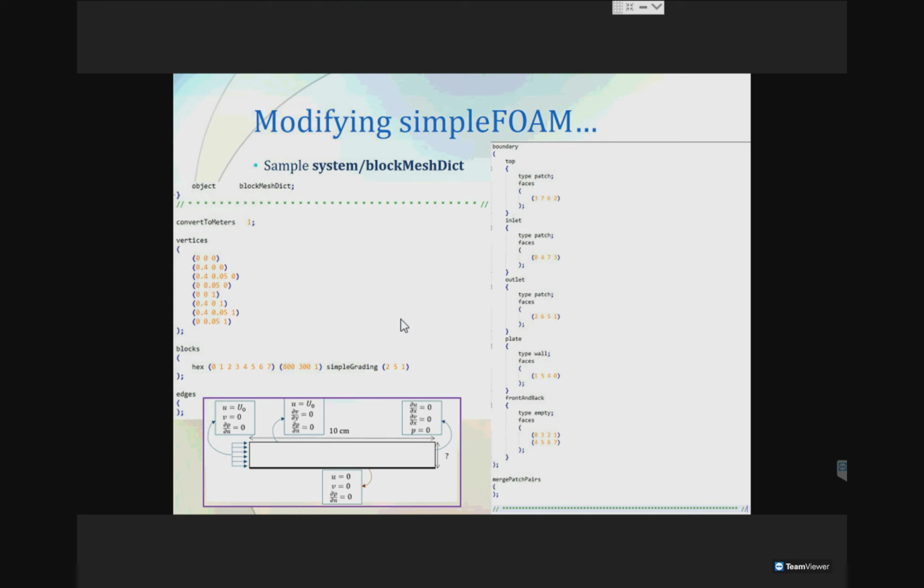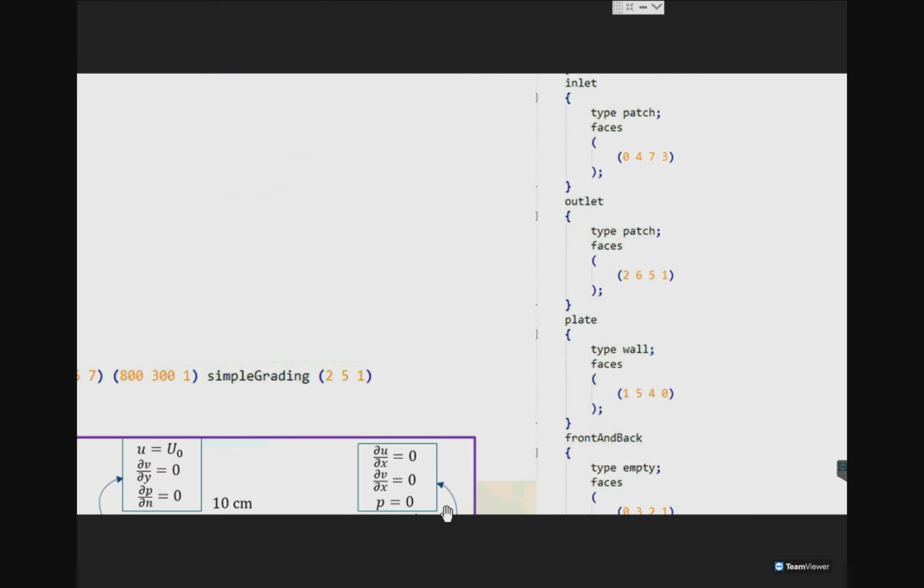So what do we want? We want more mesh. If we consider the y direction, we want a finer mesh at the bottom and a coarser mesh at the top. So since we want a finer mesh at the bottom, we want a smaller delta S and a larger delta E. So that is why I am specifying for the y direction, I am specifying 5. If it's not large enough, okay.